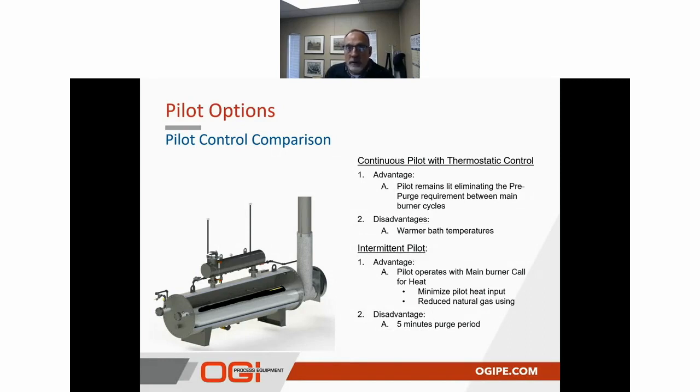So if you're in a cycle period, let's say a shoulder month operation, where that burner has to kick on and off in less than 5 minutes to keep up with your capacity, it will actually fall behind in operation if it's not able to keep up, which is going to cause you to have to adjust some control set points higher to provide you some grace in your control.